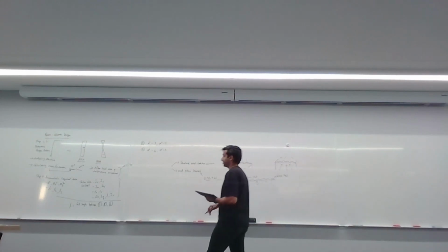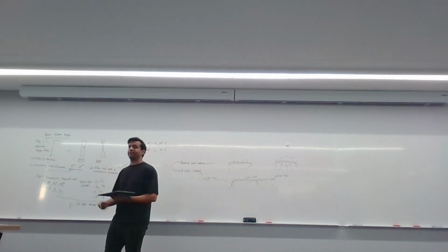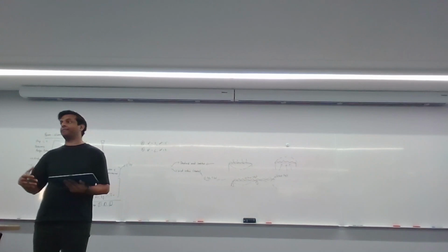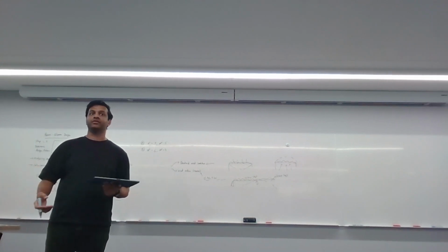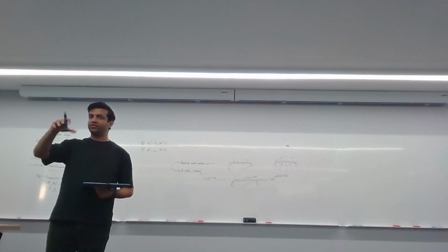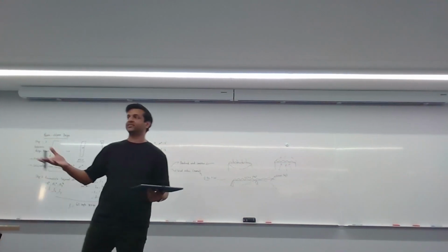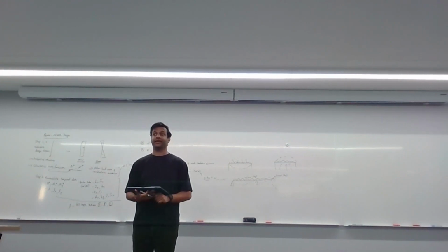Now the next thing is, yes, you've got to know what it looks like. What are some possible examples of a full restraint? What are some examples of a partial restraint? Those are given in the code, AS4100. So if you have AS4100 with you, just have a look there. They would have given you different sketches of what different types look like, and I'm sure the lecture notes have some examples as well of what some of these different section details look like.